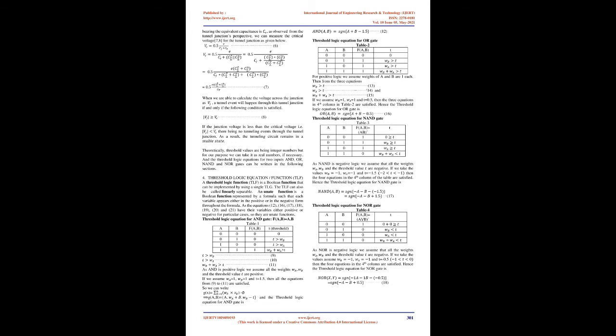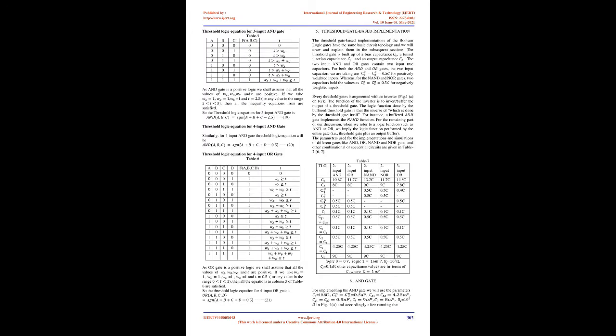The island of each SET has a size smaller than 10 nm diameter of a metal like gold, and their capacitances must be less than 10^-17 F. The output terminal is connected to the common channel in between them and to the ground via a capacitor to suppress charging effects.